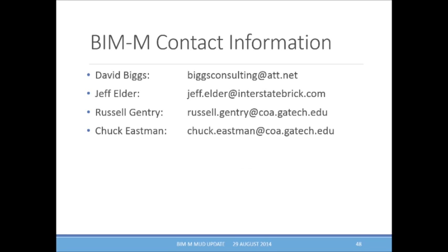Okay. Yeah, this is Russell. I'm going to follow up with Jeff's answer and say that the larger structural clay units are something that we at Georgia Tech don't understand as well, and we need a little more education. Sometimes we look at it as a clay material with the CMU geometry. I know that's too simple, but we can easily make it more clear. But I would stress that any kind of architectural block unit as well as a standard gray block unit in the CMU industry is fully represented in the database. And we know that there will also be thin units. There are thin units being made right now that are 1 inch or 1 1/4 inch faces that will be anchored. So those will also be included.